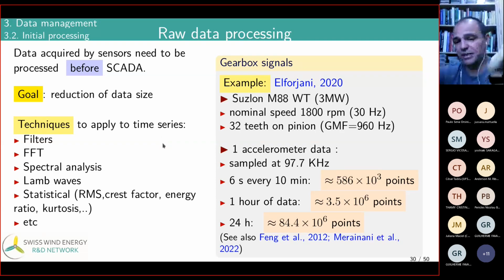Time series, so you can talk about vibration. If you are monitoring the turbines, vibration will be okay, but we will not observe cracks with a single accelerometer on the blade, for example. Okay, so we need some other kind of sensors.